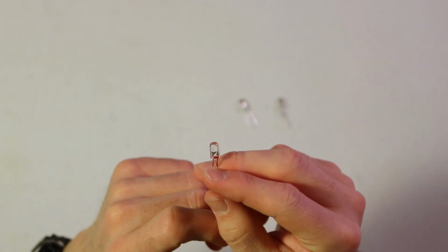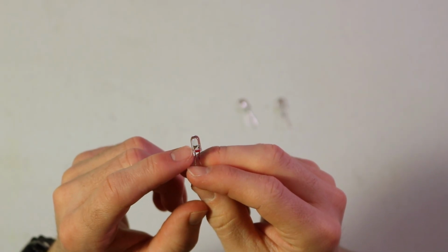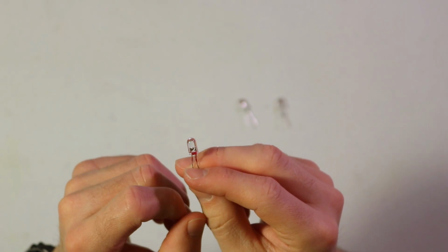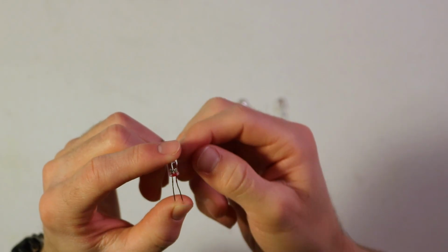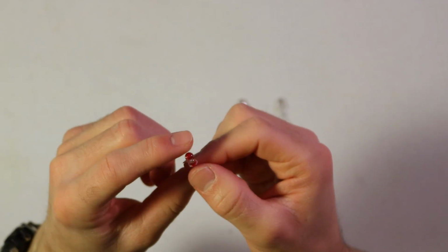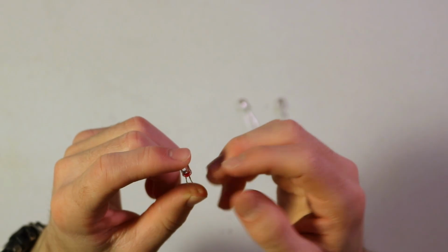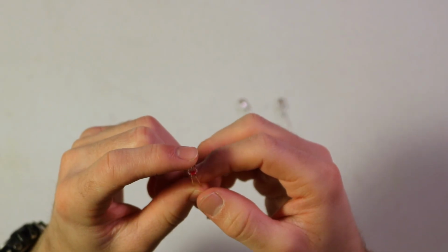Also in the case of these clear LEDs, you can see inside them, and the larger metal side, which looks like a little metal triangle, is also on the negative side. So make sure you put it in the correct orientation. If you don't, it's not going to turn on. It's not going to hurt anything unless you apply a really big voltage to it, but it won't turn on if you don't put it in the correct polarity.